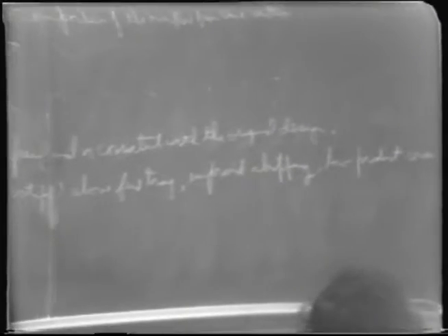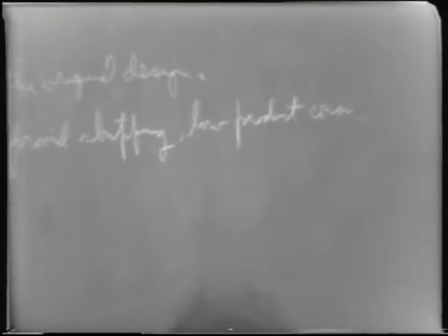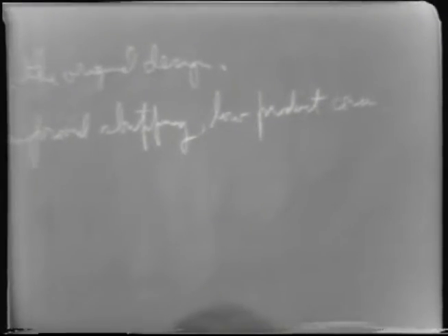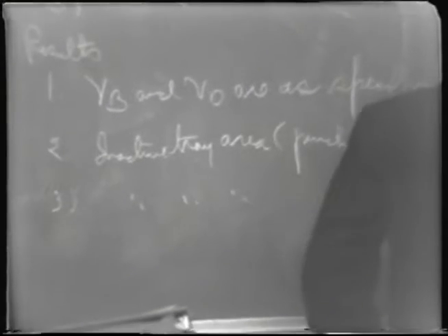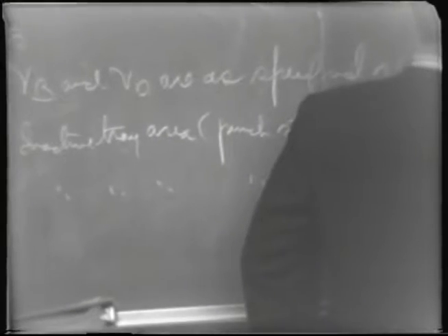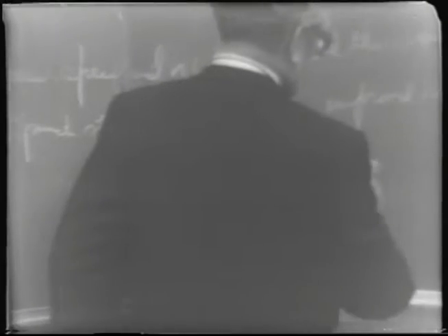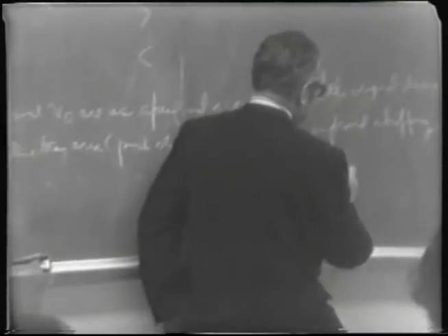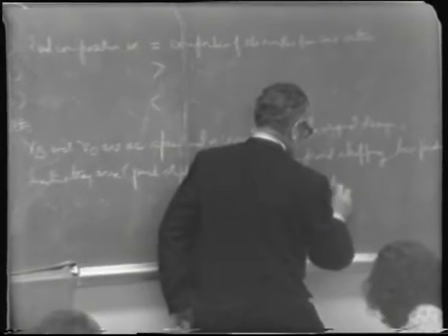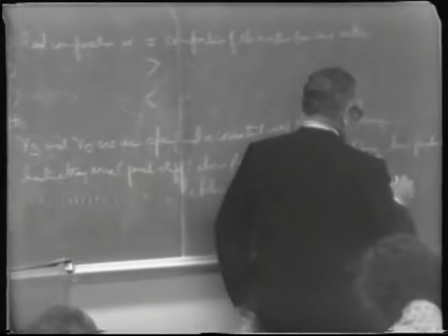And case 3 results in an inactive tray area below a series of pinch steps below the feed tray. And less effective or incomplete stripping. But a somewhat higher product quality or higher product concentration.